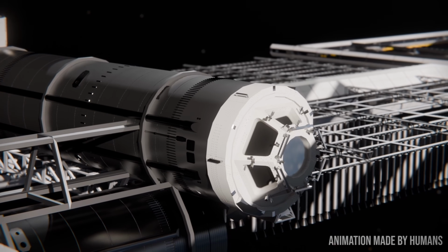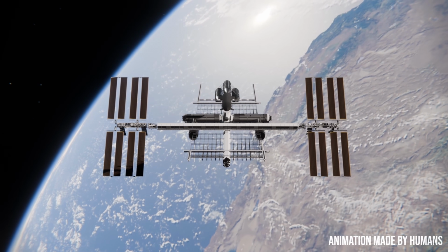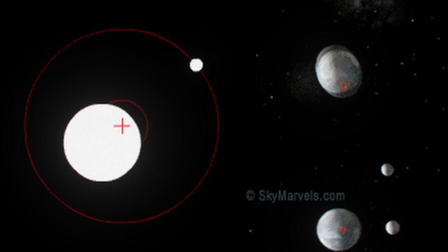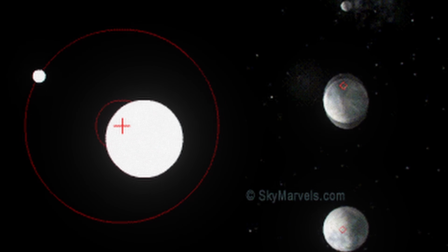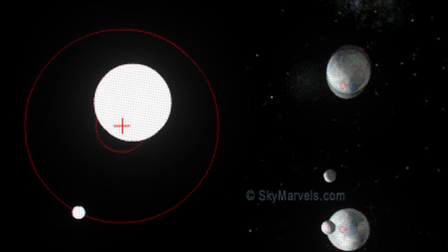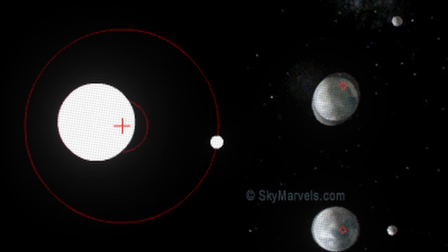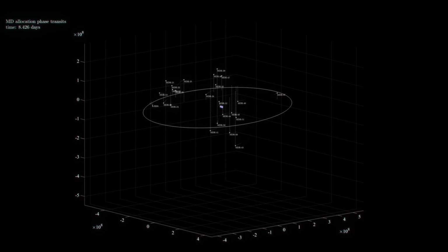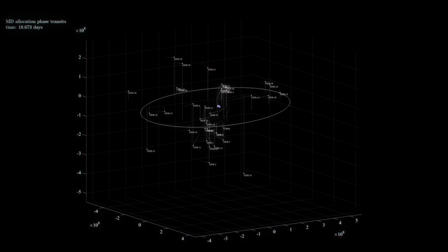Like, where do we actually locate it in Earth's orbit? And then, since smaller but faster launched rockets is better in terms of power systems, as we've just established, we can add another question, which is that of access windows. Since the Earth and the Moon are both revolving around the Earth-Moon barycenter, which makes transits through the Earth-Moon orbital system more complex than the regular elliptical Keplerian orbits we're familiar with from high school, this introduces the question of whether it's always possible for mass driver launched rockets to reach their orbits, or are there limited flight windows that we have to fly through? Can we design a collection of transits, a transit constellation, such that we could potentially reach our receiving station no matter what?